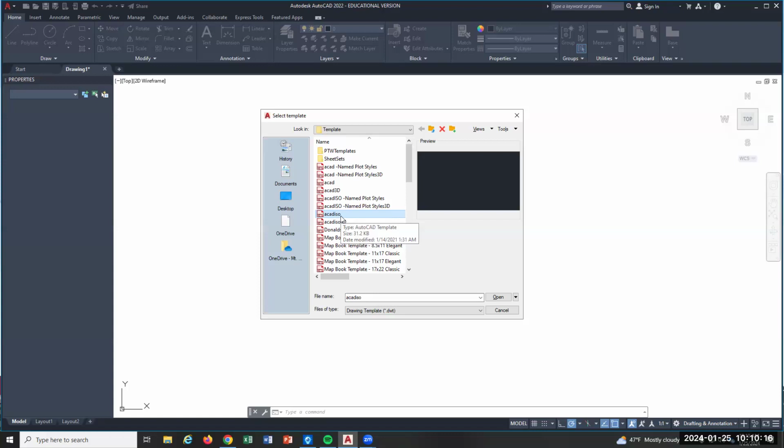Systems International. Okay. If you want inches, it's ACAD. If you want metric, it's ISO. All right. Just grinding that in a little bit here. We will do metric drawings. The first one's not, it's in inches. So I'm going to go ahead and choose.